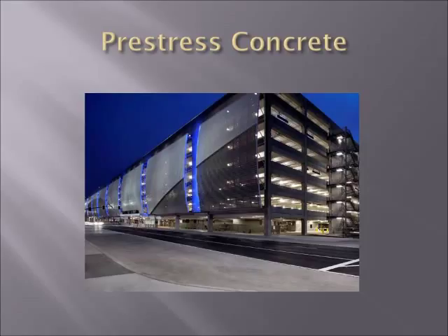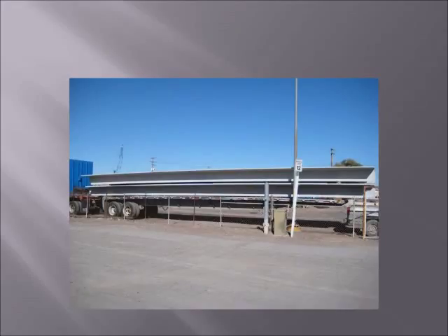Prestressed concrete is another area where structural lightweight concretes are commonly found. Not only does the reduction in dead load offer a potential for longer spans or increased widths of a prestressed member, but the reduction in transportation is far and away the biggest area of improved economy. By being able to load more pieces for every load leaving a facility, transportation costs can be dramatically cut. This also translates into improved erection efficiencies and less site congestion.